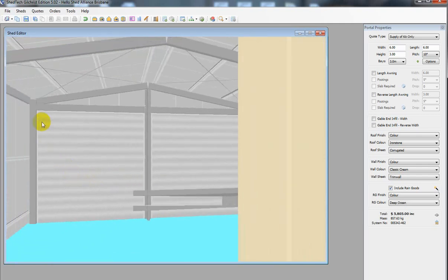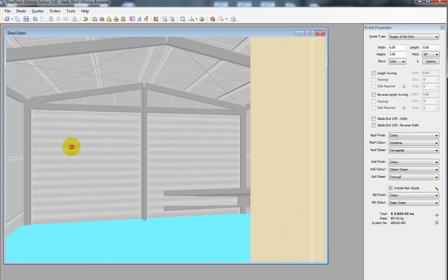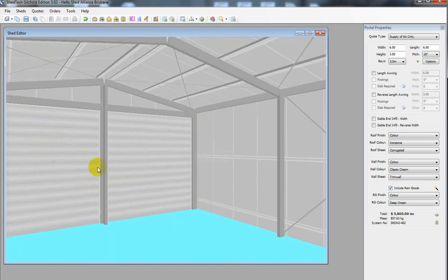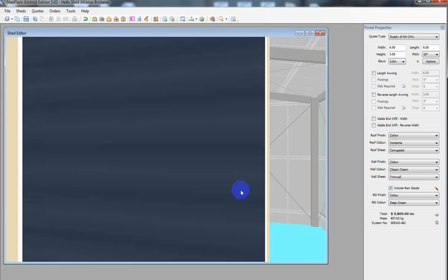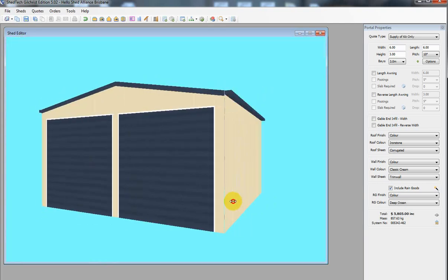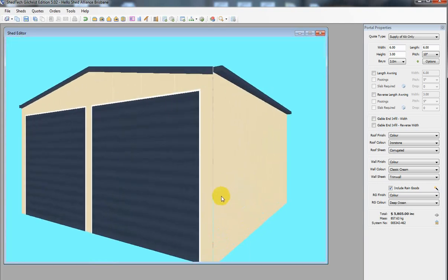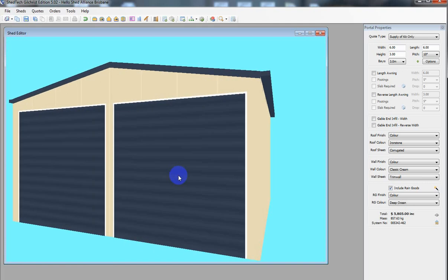So what they're doing is the track is running at the sides on the corner post of the shed, and it has a separate mullion. The mullion itself has another stiffening mullion to stop wind blowing in on the gable ends, which is part of the current routine of how we have to design a shed. Of course, we are shed safe, so there's no corners cut, and that's what we've got to do. So that's now put two 2750 by 2750 roller doors in the gable end.